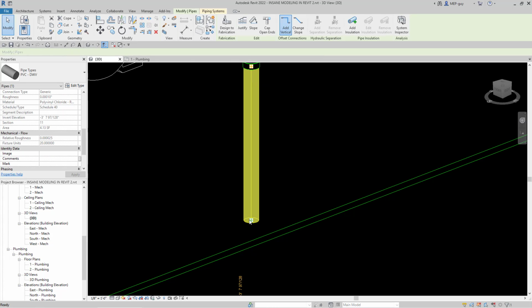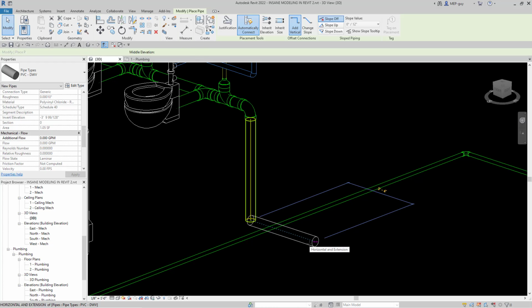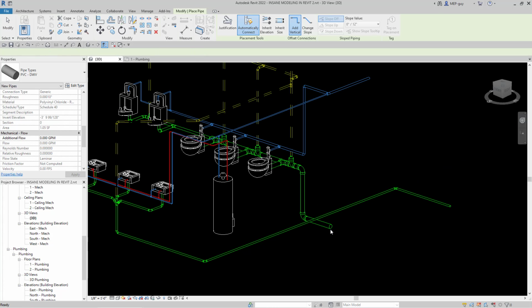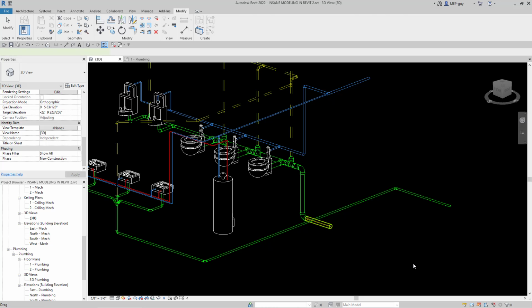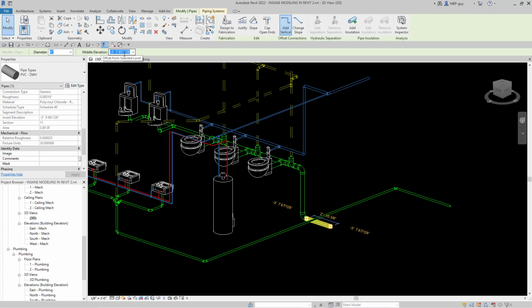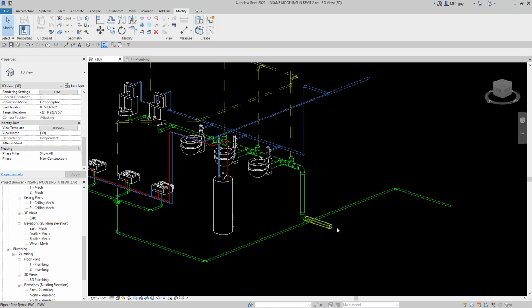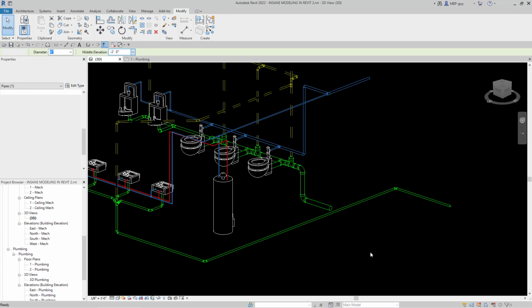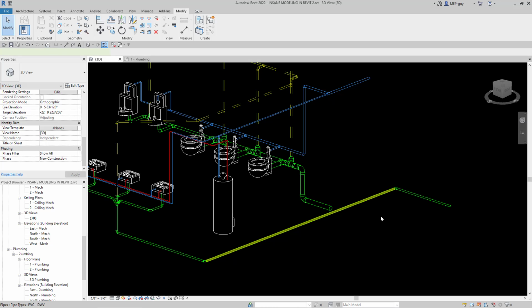Now we're going to draw a pipe, and we're just going to hold our shift button to make the pipe just like that. And we'll make sure that we make this piece, which is at -2, I believe. Well, we got to change that to -2. My Revit's being really slow on me, guys. I'm sorry. So let's make that -2. Let's just use the drop down this time. All right, and these two should be at the same elevation now.